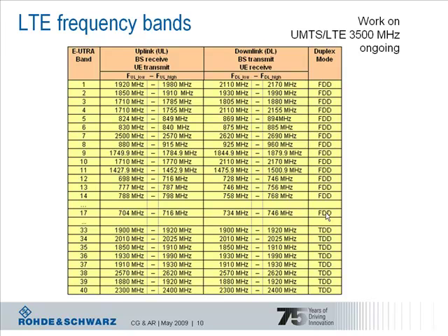There's some prioritization already defined for band 1, which is the existing UMTS band, band 3, band 7, which is the 2.6 GHz band, and band 13 in the 700 MHz arena. For TDD, band 38 and band 40 have a certain prioritization for real network deployment and for the first commercial deployments. But in principle, LTE can be operated in all these frequency bands.